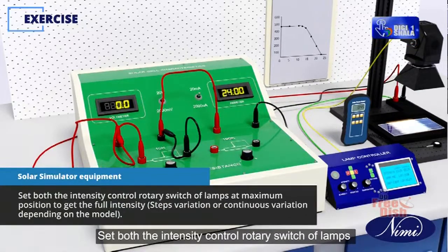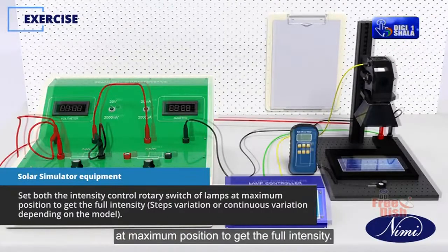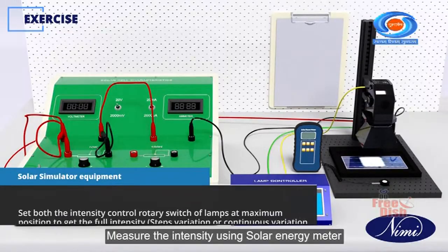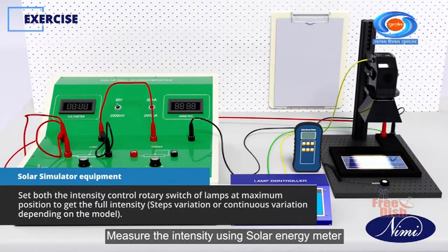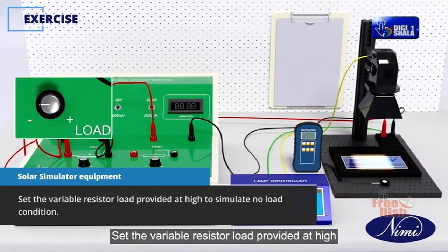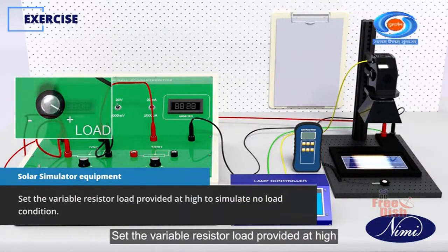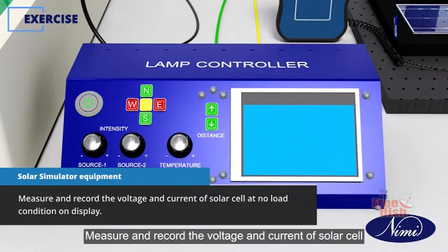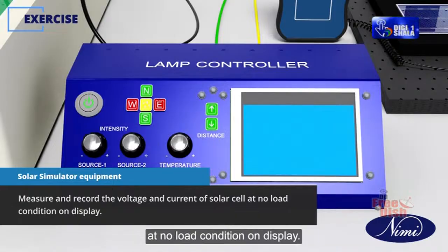Set both the intensity control rotary switches of the lamps at maximum position to get the full intensity. Measure the intensity using a solar energy meter and record the observed value. Set the variable resistor load to high to simulate no load condition. Measure and record the voltage and current of the solar cell at no load condition on the display.